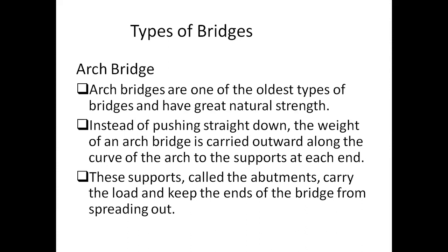It is a counteraction to the beam deflection. If you take a longitudinal beam, when it bends, it will bend towards the downward side. Arches will be a reversal of the beam deflection. That's the reason why arches have more load carrying capacity.